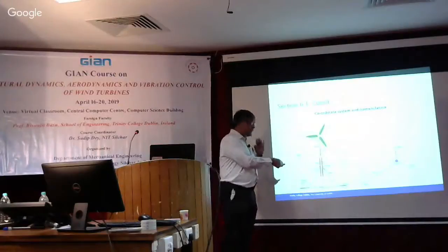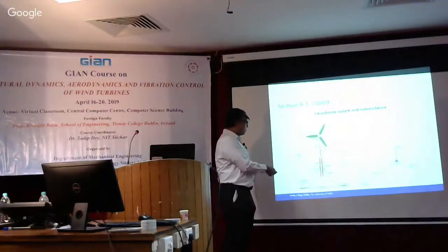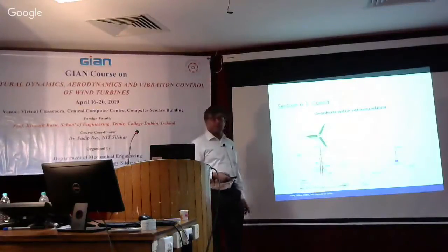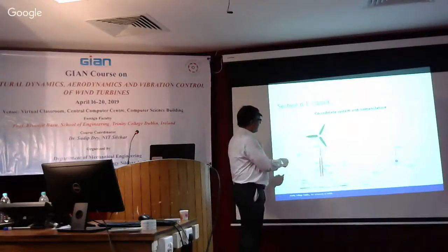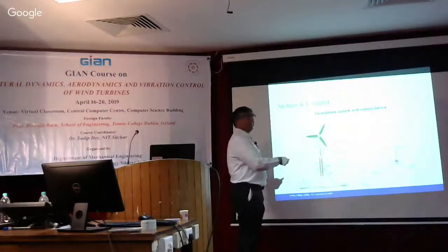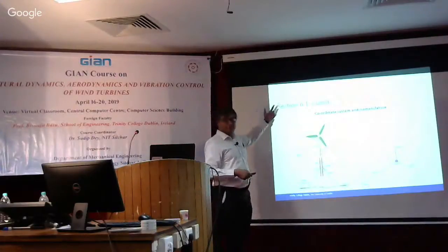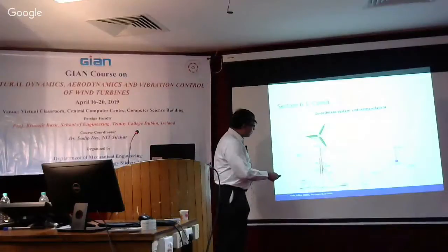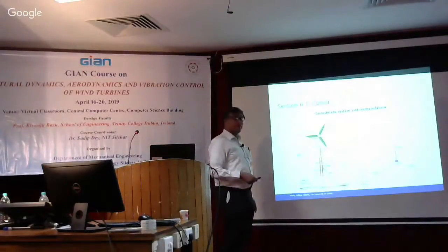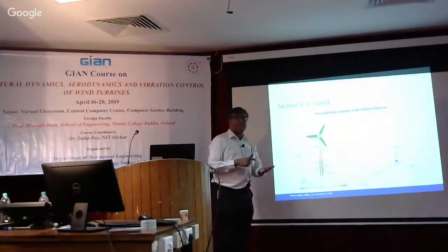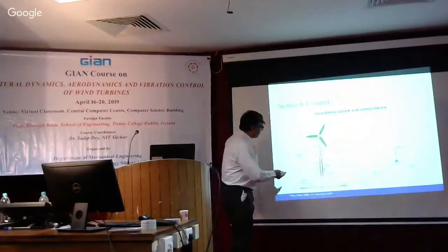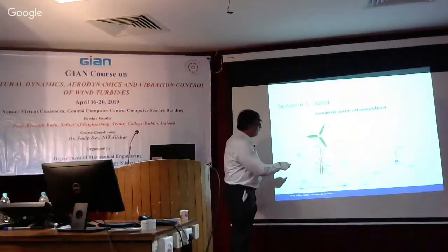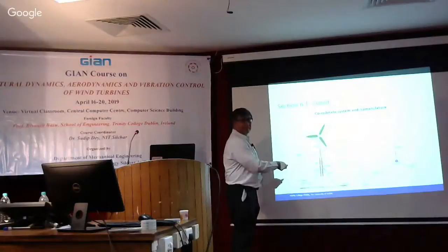So there'll be a kinematic boundary condition, but also a dynamic boundary condition as well, because you know that on the surface here you have atmospheric pressure, so that is the dynamic boundary condition. But here you don't have the pressure, so that gives you the dynamic boundary. So you have kinematic and dynamic boundary conditions. The kinematic boundary condition is that the velocity here has to be 0 or equal to the velocity of this surface. That's the kinematic.